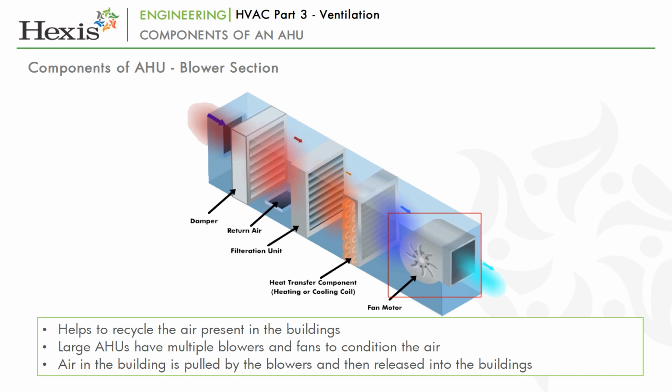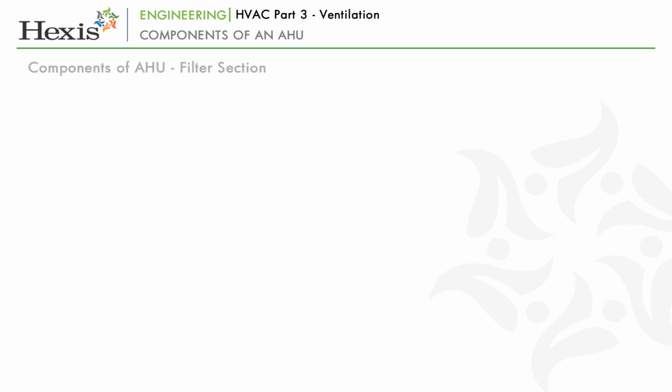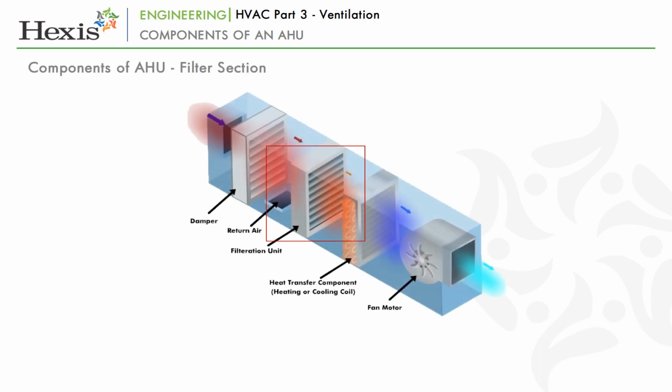The fan and motor is normally mounted on a common channel fitted with anti-vibration isolators to avoid the vibration transfer to main casing. Filter section. Filters include plate filters, bag filters, compact filters, EPA filters, HEPA filters, ULPA filters, and carbon filters.